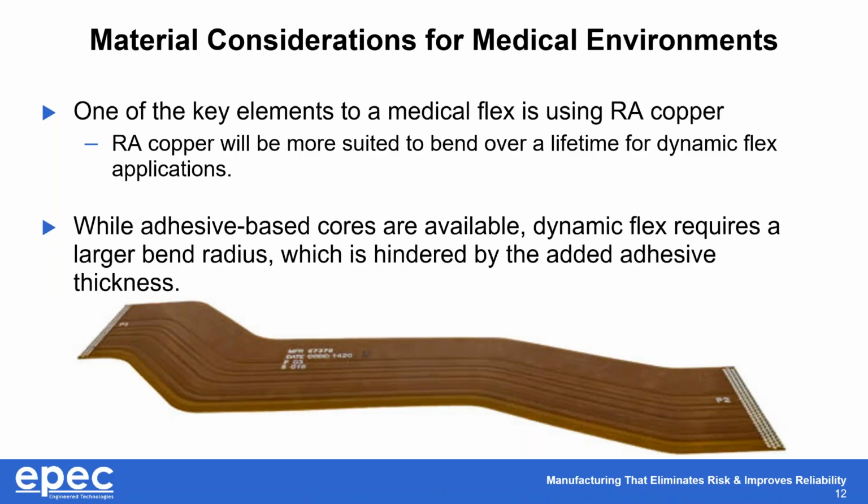And while adhesive-based cores can be available, where an adhesive-based core might save on money or availability, dynamic flex requires that larger bend radius we touched on earlier, the 100 times the thickness, and that can work against adhesive-based cores because they have the added thickness. So almost entirely we will recommend adhesive-less cores for dynamic flexes.